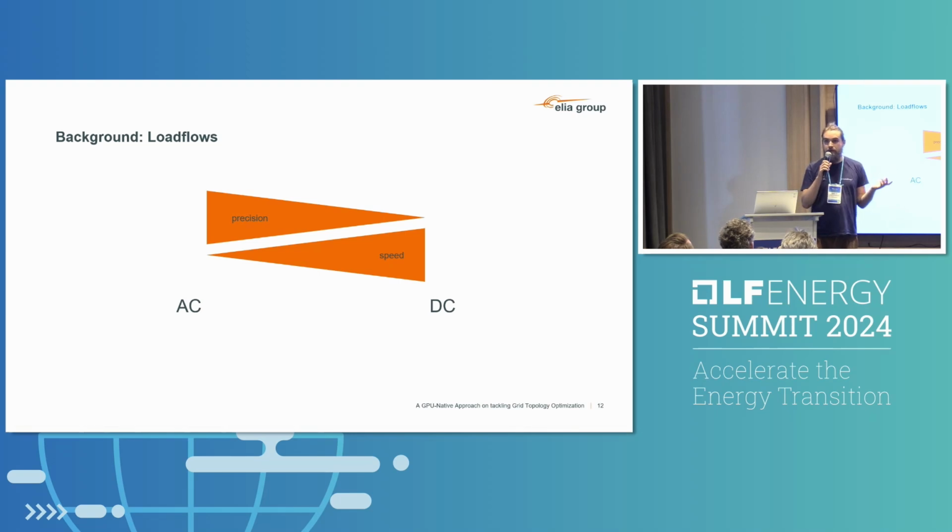Unfortunately, we don't know unless we compute Kirchhoff's and Ohm's laws. So that's basically the idea behind the load flow equations. There's just Kirchhoff's laws. You can compute the full equations. That's called the AC load flow. That's currently one of the best approximations of what's actually happening on the grid, the steady state load flow at least.